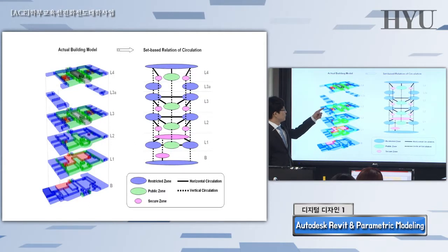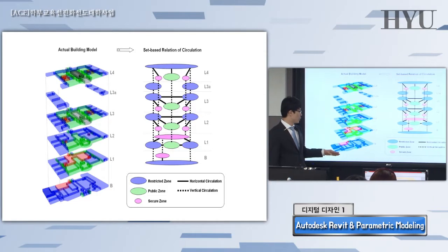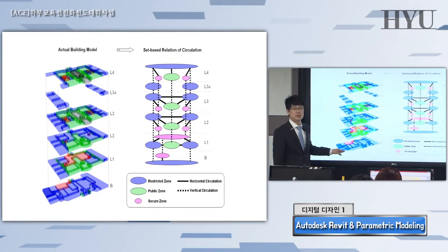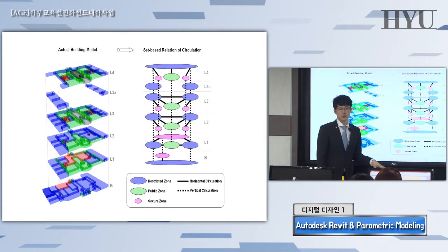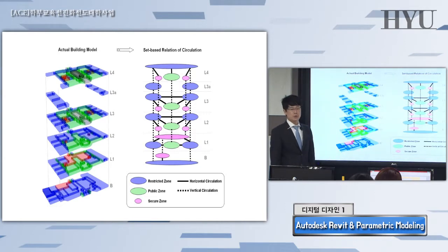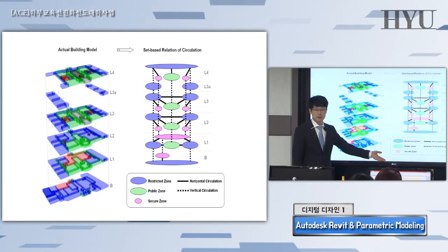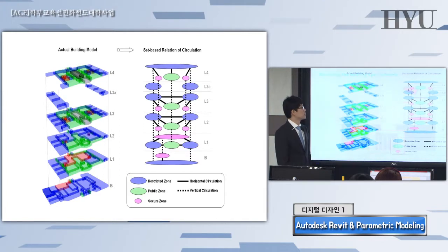And this is some old data of space objects. I told you in BIM, there are space objects without any doors, walls, or slabs. Only by modeling space objects, we can create this kind of building shape. And we can generate additional diagrams to review circulation and security issues. The computer knows whether this red space can be accessible to this green space or not, in automation, and reports if there is a problem.